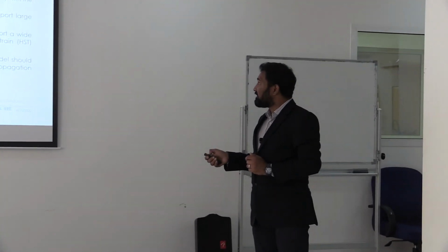So these are the new requirements when we are going for the 5G channel model. One is the wide frequency range, the broad bandwidths, a wide range of scenarios, then double directional 3-dimensional modeling. The double directional, as we said, means both transmitter and receiver are moving with respect to the scattering parameters. Then a smooth time evolution, and spatial consistency. This is the one we are going to concentrate on today. How we are going to maintain the spatial consistency between the transmitting antenna and the receiving antenna when we are implementing these MIMO receivers in different use cases.